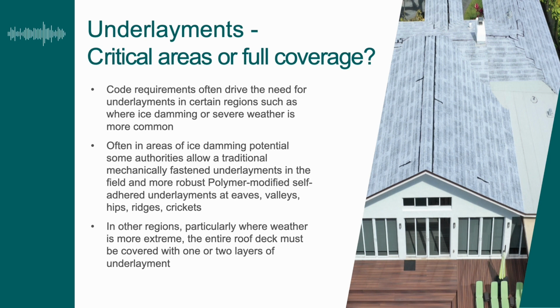So speaking of that, is it beneficial to have underlayment just in those critical areas on the eaves and valleys and rakes, or is full coverage desired or required? So code often drives the answer to that question. In certain regions where ice damming or severe weather is common, it's actually mandated by code that the underlayment cover the entire roof deck, specifically to seal the deck.